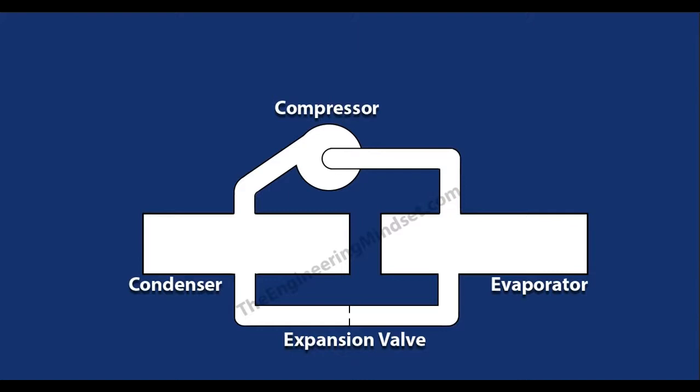Now, there are three main circuits in a chiller which you also need to know about, so write this down as well. We've got the refrigeration circuit, the refrigeration loop, and this is the refrigerant which passes around each of the four components and transfers that heat from the evaporator over to the condenser and back again. A constant loop, getting the heat out of the building and over to the condenser where it can be sent